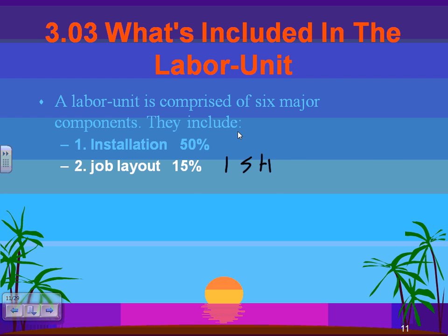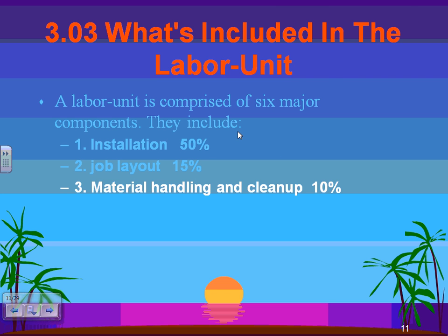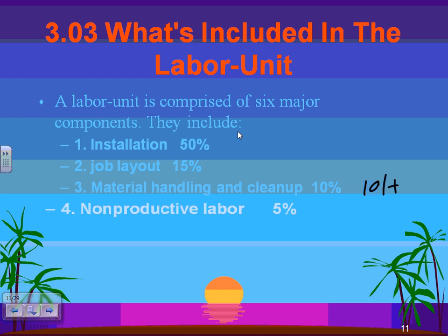From $100, take the second one: material handling and cleanup. You need to grab the equipment and the material, handle them, put them there, and clean up behind you. That's 10 hours. Well, that's a lot in the example that we gave, but let's just say 10 hours just to do the cleanup after all the stuff that you did, based on the example that we have, which is 100 hours for switchgear. Cool, 10%. The non-productive time, 5 hours, based on the example.